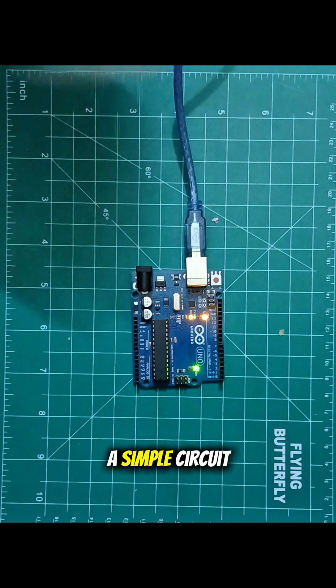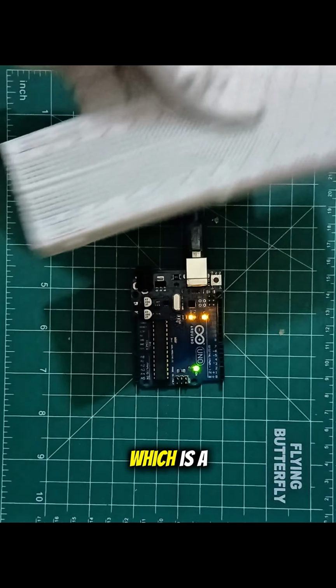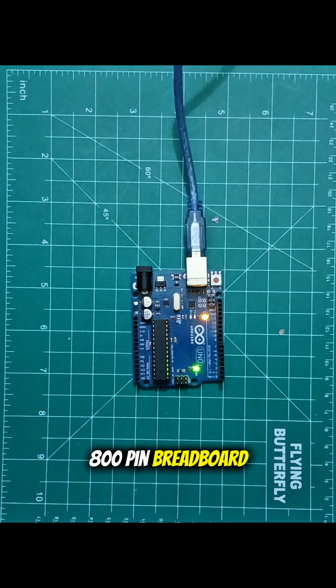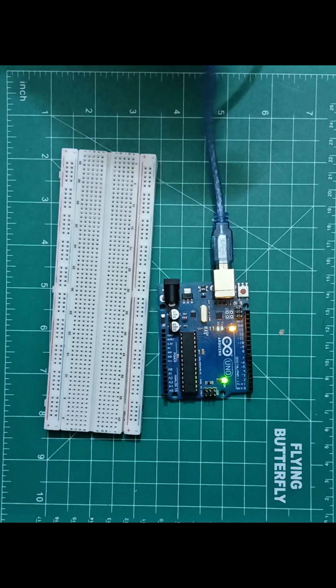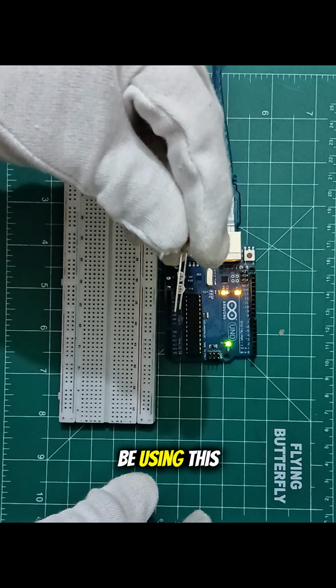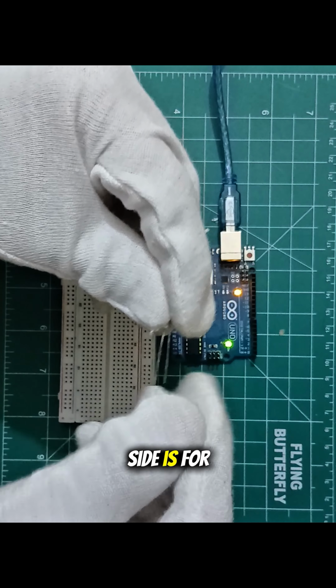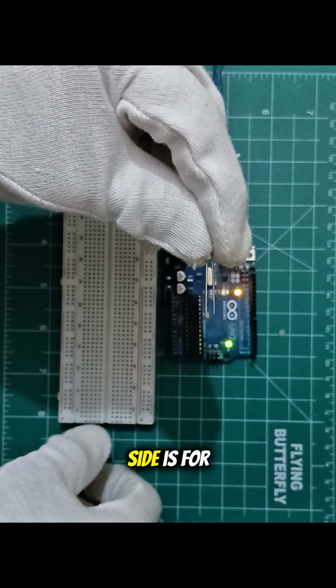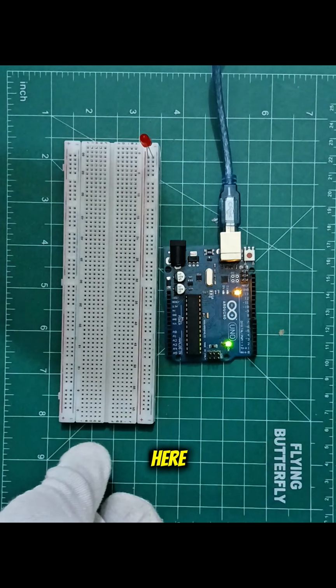Now let's make a simple circuit with this Arduino. For this we're going to be using this breadboard, which is an 800 pin breadboard, and along with this breadboard, we will be using this LED. There are two pins. The longer side is for positive while the shorter side is for negative. Then we will be connecting it here.